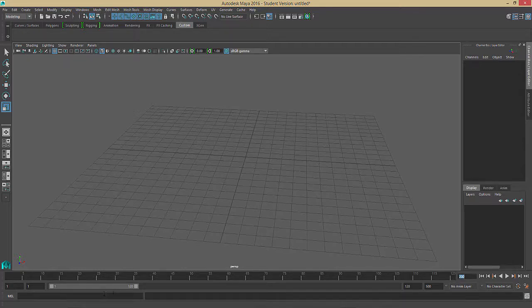200 and I can't see 200 because I only have 120 frames visible. However, you'll note that if I look here in my range slider, it says your start frame is 1, you're currently viewing 1 through 120 in your frames. However, you do have more frames here because you're just viewing to 120, but really you have 500 frames. So you can type in however many frames you want in there. So now I typed in 400.